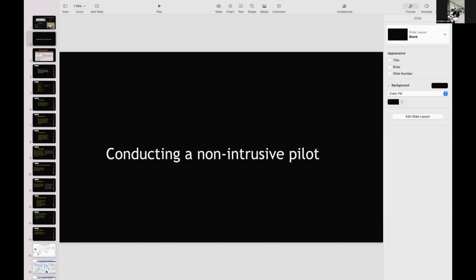So we'll detect a physical insider who actually turns a valve off, correct? Absolutely. So, for example, if you turn a valve off when the water level in a tank is very low and the pump is running, the pump will have to stop at some point in time because the water is not flowing into the tank and the tank water is going down. So that will create another problem. And that will be immediately detected by our technology. That's a very simple attack to detect, actually. The more complex attack is you turn the valve off and you also tell the controller, the PLC, that the water level is good enough for the pump to run.